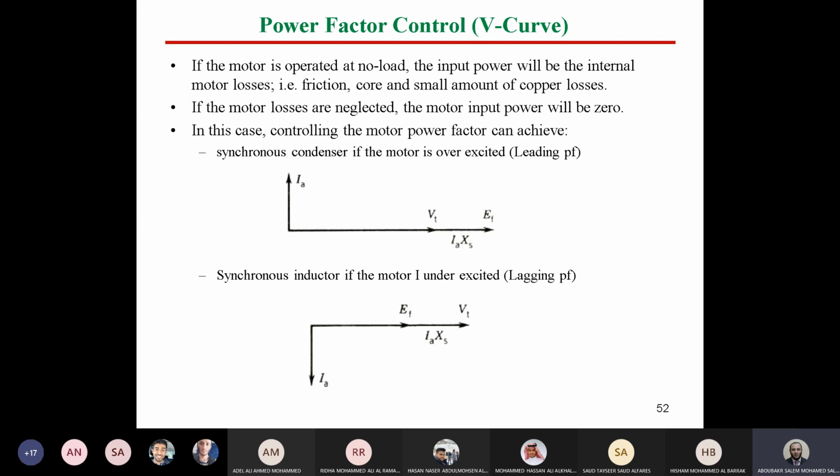It will include also a very small resistance called equivalent resistance or series equivalent resistance for the capacitor itself. So we can say now the synchronous motor at no load is like a capacitor, even a practical capacitor, where a practical capacitor as well is not purely capacitive. It has a very small equivalent resistance as well.